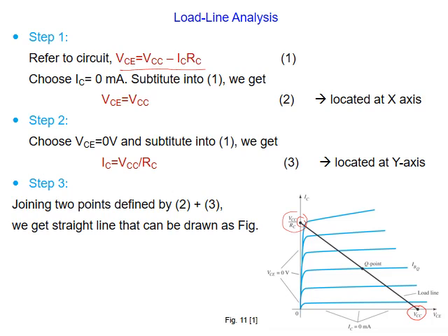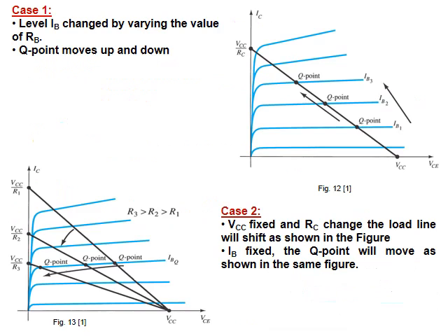Now we go to the input characteristics. We got IBQ. If we know the IBQ, as an example, this line will be used, then this point of intersection represents the operating point. Here VCEQ, and here ICQ. You got it? It's also a procedure.